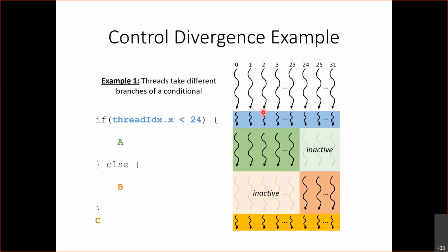So obviously there's an inefficiency here because I have these cores that are wasted because of these inactive threads. I can't do anything else with these cores because they are bound to the cores that are executing the other threads by the same instruction dispatch unit. Is this clear to everyone? Questions? Yes. Are there techniques to improve, like compiling techniques to improve the warp dispatching or scheduling in order to minimize those inactive times?